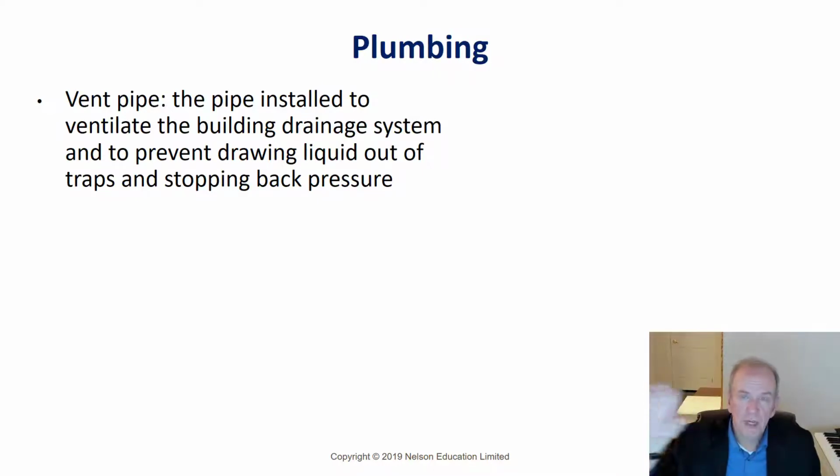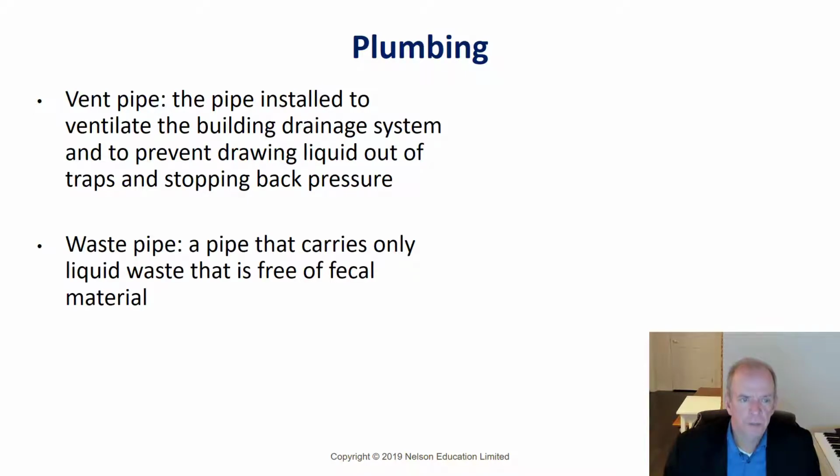As well, a vent pipe you can kind of think of, it's going to allow your sinks to drain more quickly. It's kind of like a Tetra Pak. You know when you put a straw in it and you suck on it, it's kind of squeezing the box. Well, if you put a hole on the other side, it'll very easily empty itself and it won't be so difficult to pull it. Well, a vent pipe is very much like that hole that you would put on the other side that allows it to vent, and that will allow your sinks and your bathtubs to drain much more quickly and efficiently when they're sized and put in properly.